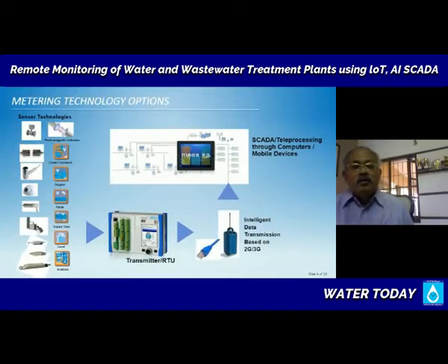So what you want is, depending on your water condition, whether it is in a wastewater treatment plant, whether it's raw water, clean water, dirty water, sewage, municipal wastewater, drinking water, river water, you want to measure it in the condition that the water is. You don't want to change the condition or adapt it for measurement. That will give you a continuous cost drain, energy drain, if you try to adjust your process for measurement.